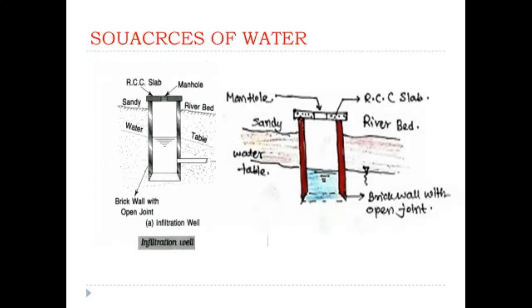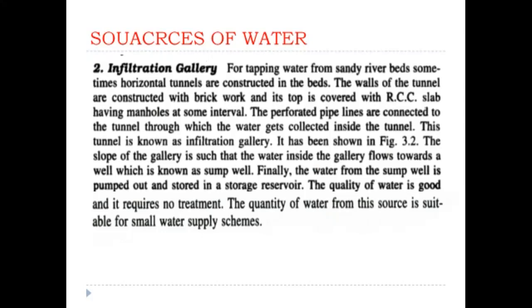Next one, infiltration galleries. For tapping water from sandy riverbeds, sometimes horizontal tunnels are constructed into the beds. These are one of the examples of underground sources. Perforated pipelines are connected to the tunnel, through which the water gets collected inside the tunnel.